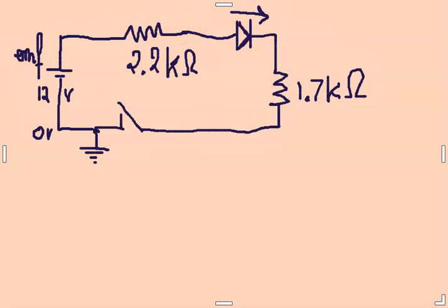So this will go this way. Since the positive is here on the longer plate, the shorter plate is negative. Conventional current goes out of the positive, so we can draw here. Let me label it as I sub naught, so the initial or the principal current. This is passing through the resistor 2.2 kilo ohms, creating a potential drop between those two nodes.